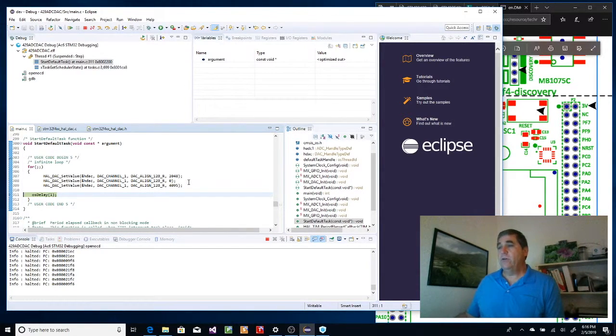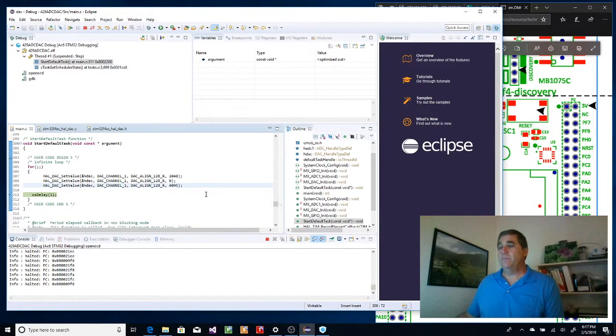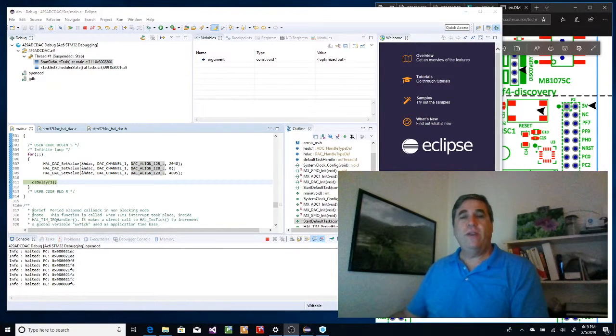So that's great. So we've proven that I can set it to center. We've proven that I can set it to 0, and I can set it to the maximum range, which is the 2.8 volts in this case. Okay, so next stop, I think we're going to start taking a look at PWMs, what they are, what they mean, how you use them, and all that kind of stuff. They're easy to understand and easy to put to use, so we'll do that next.